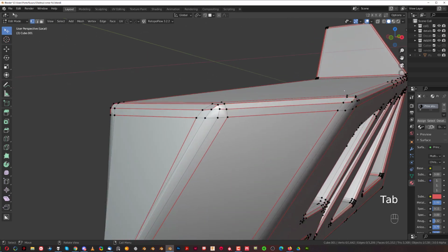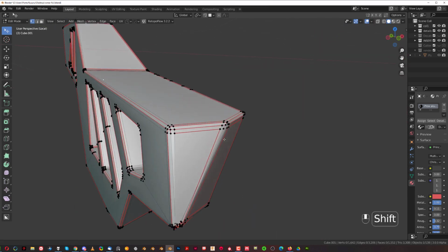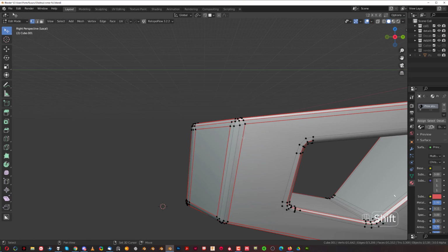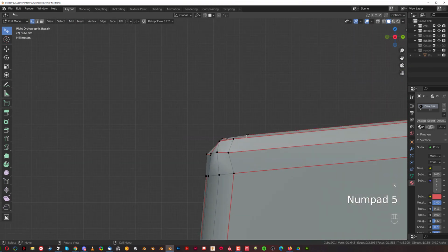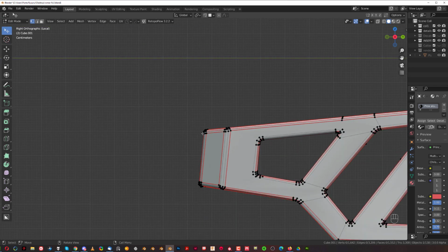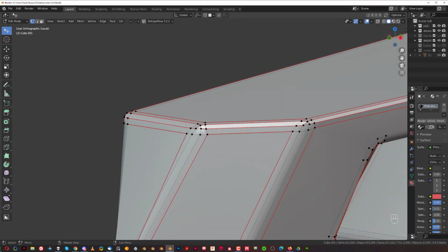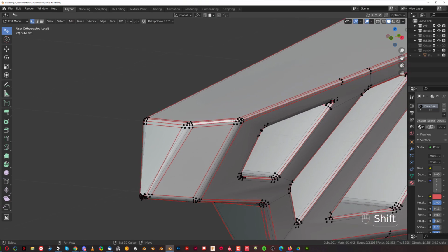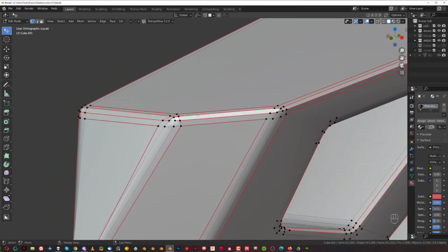So how would you even start cleaning that garbage, right? Well, first of all, what we need to do is move this plane here towards this left plane and make them meet somewhere in the middle, which is manually impossible to do when you want to maintain angles. But fortunately, there are tools in Mesh Machine that are gonna help us with this one.